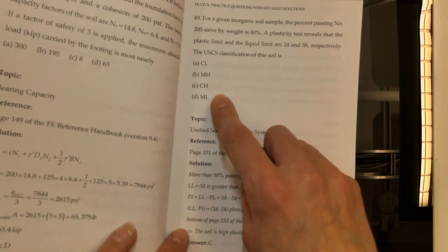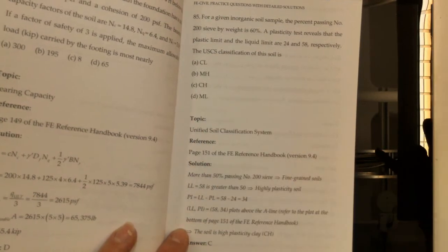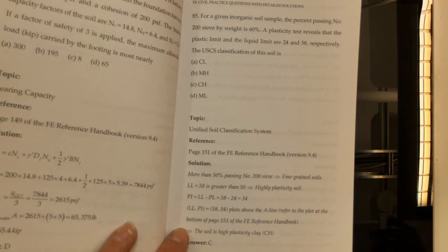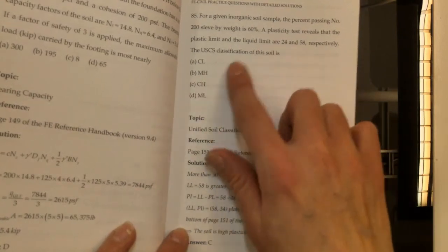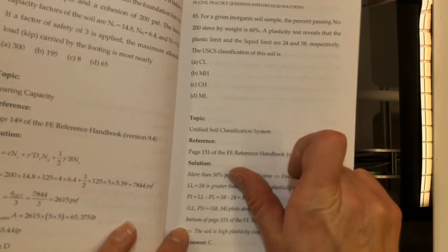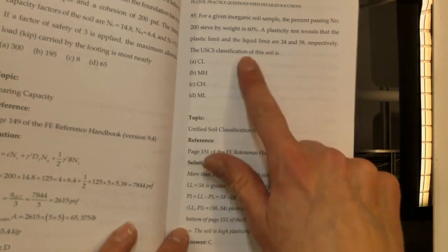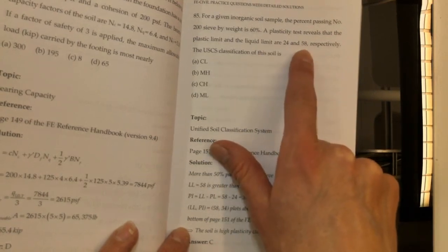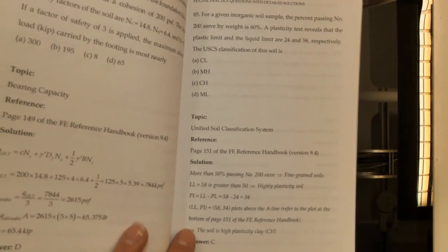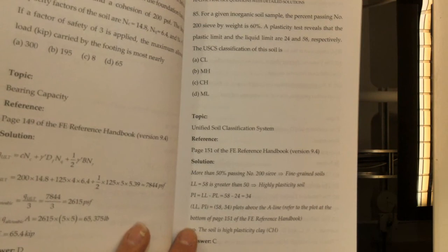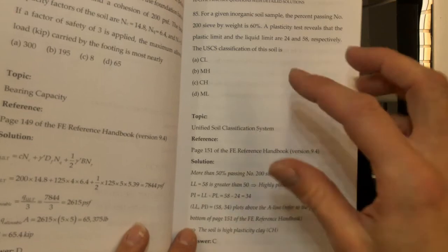That should be less worrisome than when you had to give names, because you don't have to worry about whether there is a certain percentage of sand in the sample. The practice ones I've seen for soil classification have all been fine-grained soils, so they're only giving you plastic and liquid limits, and that only brings you to the silt or clay decision in the USCS table. So it narrows it down pretty quickly.